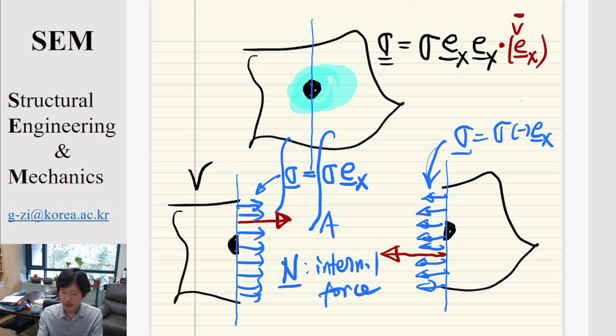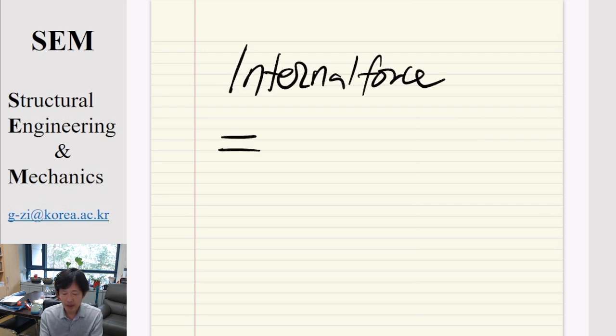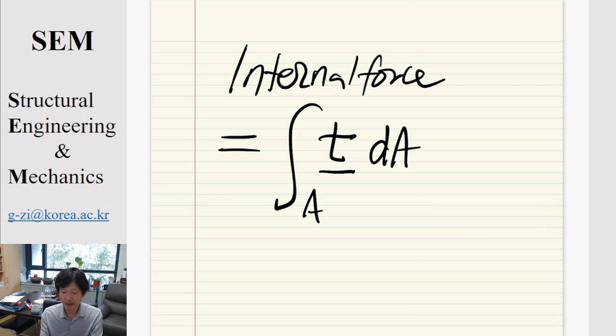So the conclusion is that the internal force is the integration of traction, developed because of the stress state, over the cross section. That's the meaning of internal force.